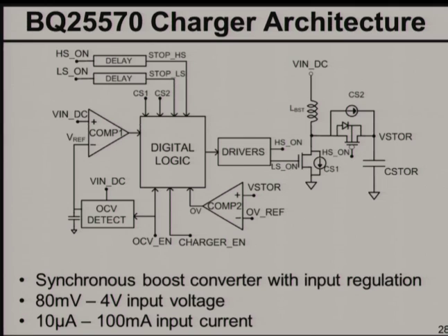The key thing here is there's no constantly on clock, so you want to minimize the quiescent current. You've got to bias these systems at a few nanoamps and remove all clocks that are in your system. And so that's what the charger itself does.